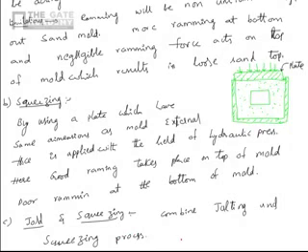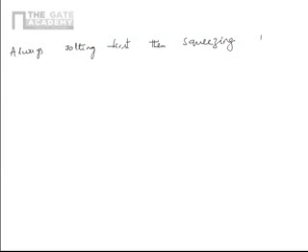Always you need to do jolting first, then squeezing, to get almost uniform ramming.